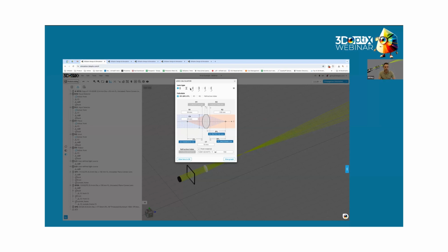So we'll start with the lens calculator. We'll do plano convex. I'm looking for R1. The width, I'll do 3. And then the EFL will do 50. And then we can see the R1 is 25.96. I'll just switch this to EFL, so I'll be able to copy this. And by the way, at the bottom, the default is NBK7.